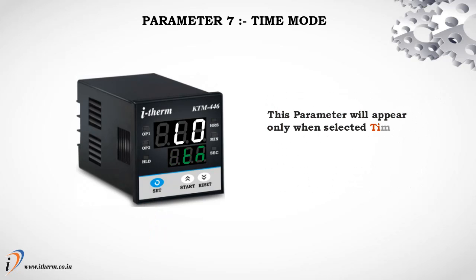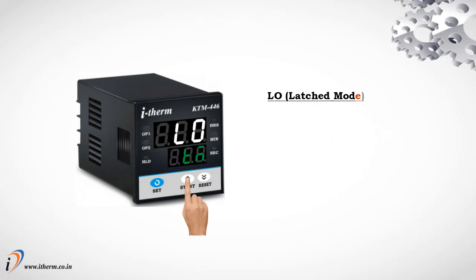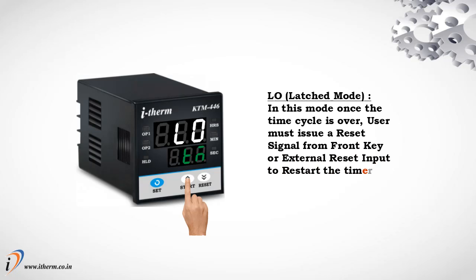Parameter 7, time mode. This parameter will appear only when selected timer function is on and off, delay and start input is other than power on start. Latched mode. In this mode, once the time cycle is over, user must issue a reset signal from front key or external reset input to restart the timer.